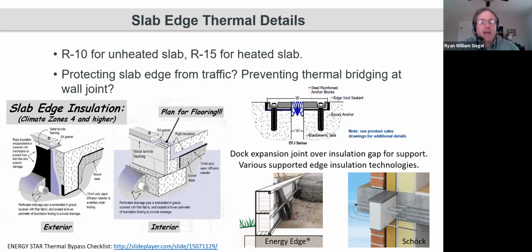and provide a mitigation to that thermal bridging rather than just bringing that slab all the way across that opening, being able to install some sort of a thermal break for that rather than just having, if you just put your 2-inch insulation in there and had it exposed, it would get damaged, not to mention the surrounding substrate would be damaged as well, likely.